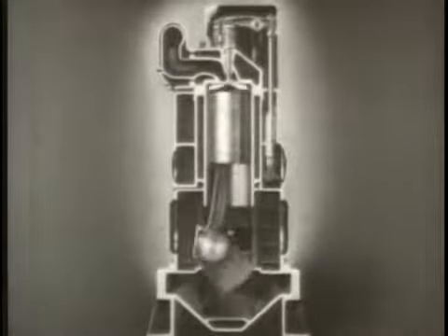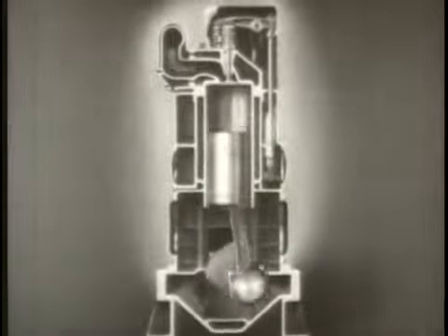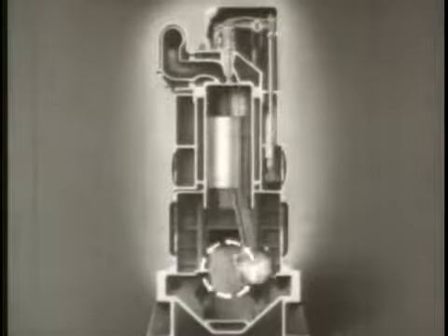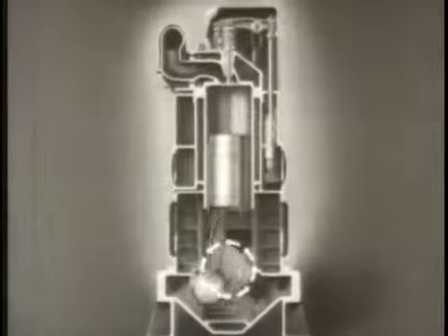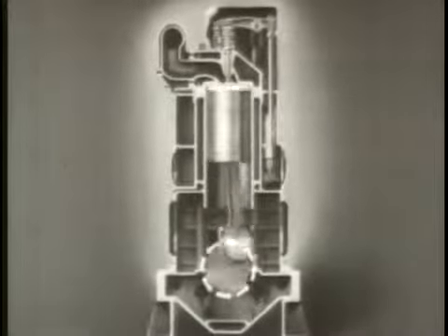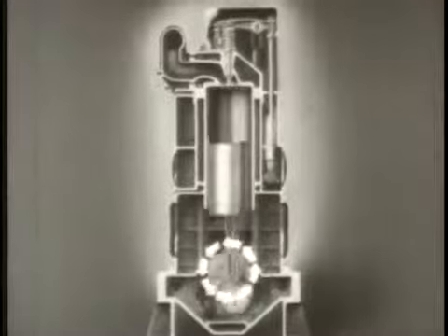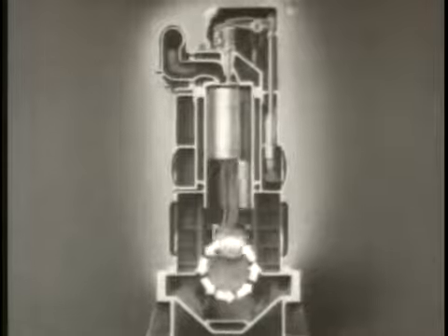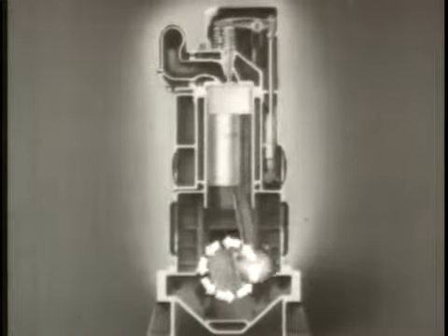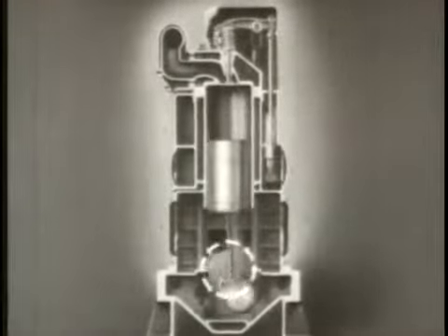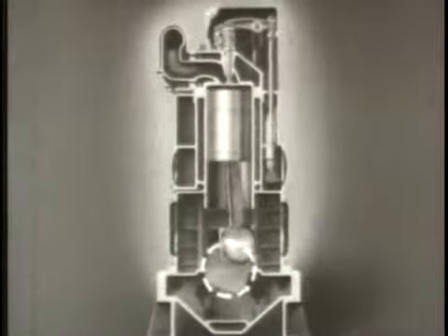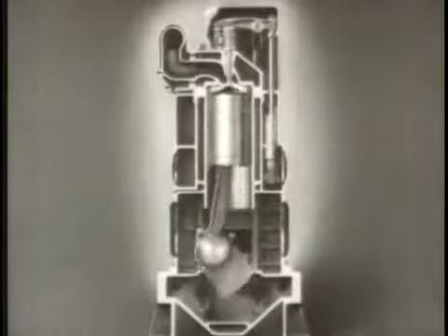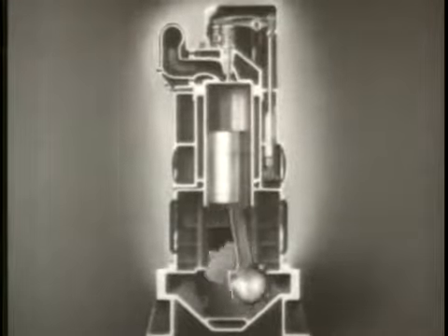The speed of a diesel engine depends on two factors: the amount of fuel injected into the cylinders and the load under which the engine works. Suppose, for example, that the engine is running at a certain speed. If the load is increased, the engine slows down. If, on the other hand, the load should decrease with no change in the amount of fuel injected, the engine speeds up. By regulating the amount of fuel injected, the engine speed may be kept within a certain range.